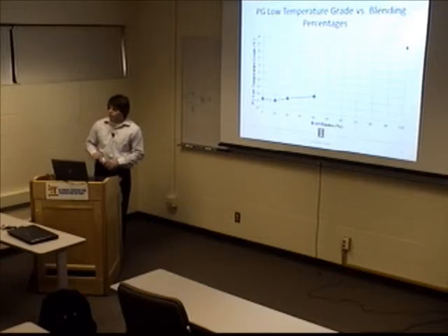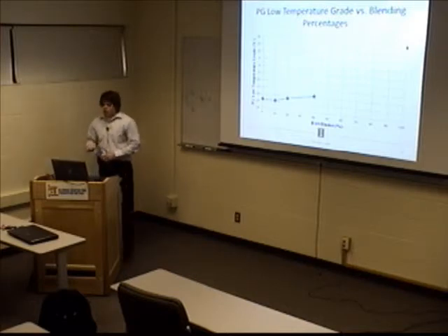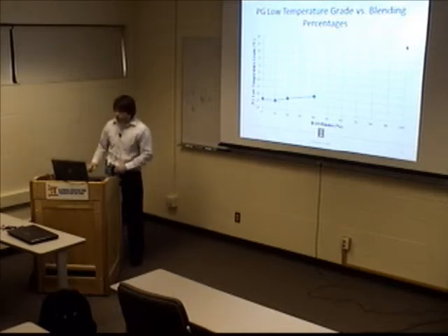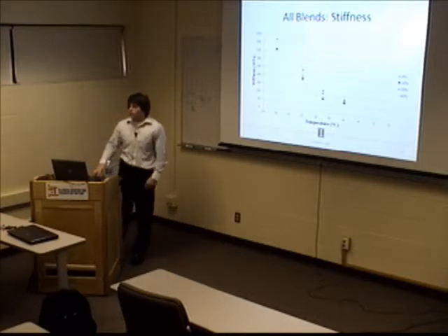Sure. I was looking at the slide where they are using a 6-inch open-graded drainage layer. That's really thick, but that's the design issue, I guess, for O'Hare. The question is, why would they be concerned about low temperature cracking in that particular layer, because it's not the structural layer? The thing is, they looked at it also from a permeability standpoint, which is obviously the main thing you want from a drainage layer, right?